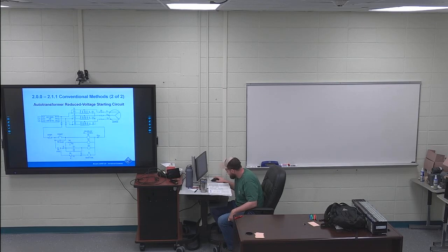The other set completes an electrical path via the normally closed contacts of contactor R and the timed open contacts TRTO of the timer relay to energize the coil of the contactor 1S. So TR closes, and then I get power to 1S coil right here. 1S will close, which closes in the power side, which closes one side of my auto transformer at the top.